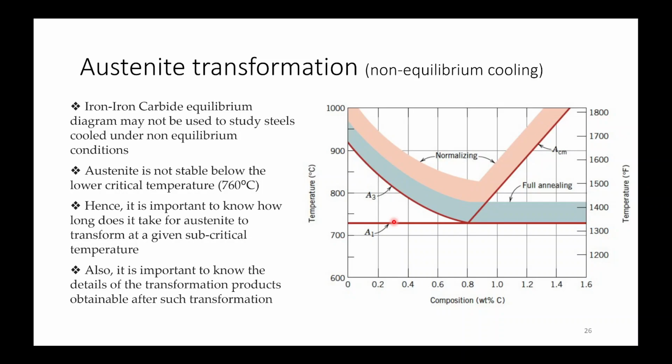In the iron-carbon diagram, three phases: here austenite, ferrite, and cementite you had at the eutectoid point. So it was three phases at that point only, at the invariant points. Similarly, even at the eutectic point it may be there: liquid, gamma, and Fe3C.